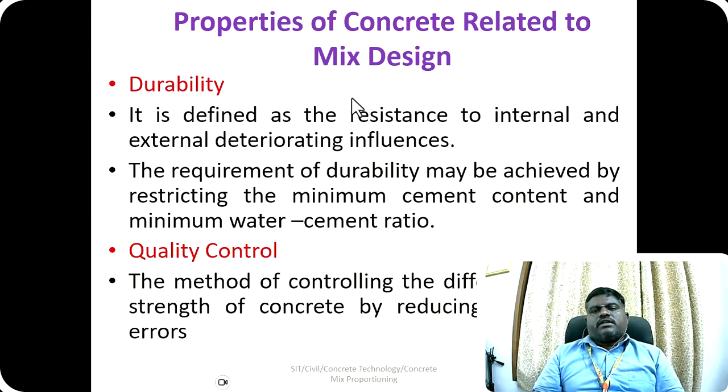The next point which affects the mix design is durability. Durability is defined as resistance to internal and external deteriorating influences. Whenever we make a concrete, the concrete should be free from foreign agencies such as chlorine, sulfate, magnesium, etc. When the foreign body enters into the concrete through the pores, it will affect the concrete. So to achieve that, we have to produce a concrete which has resistance to internal or external deterioration influences, especially chemical attacks.